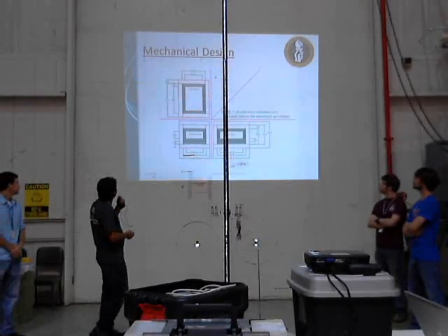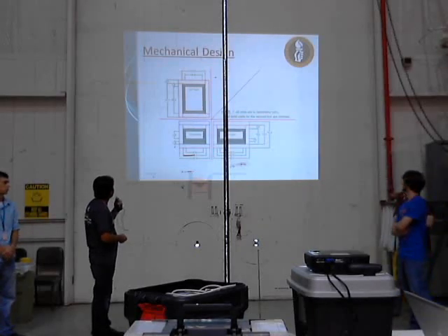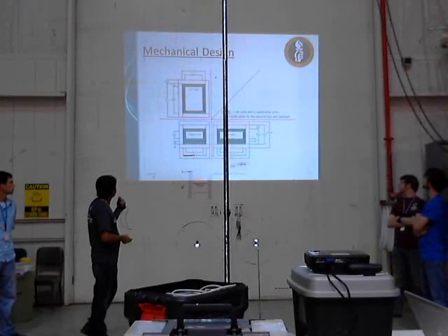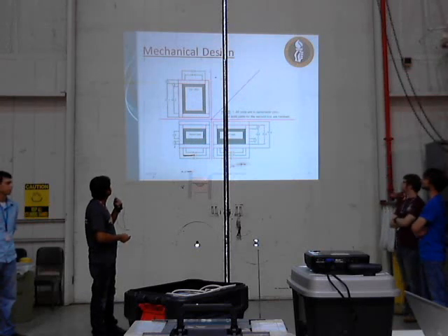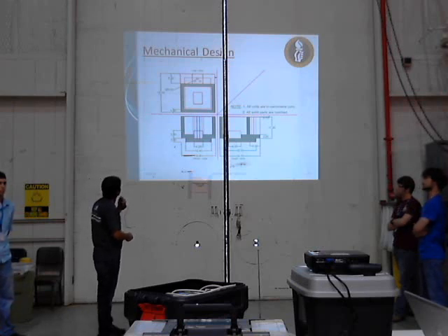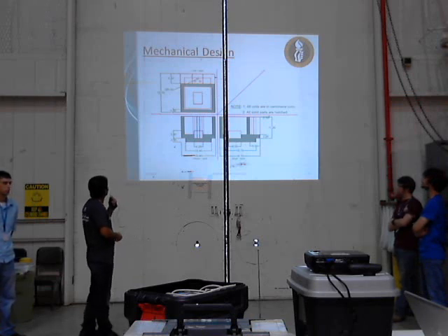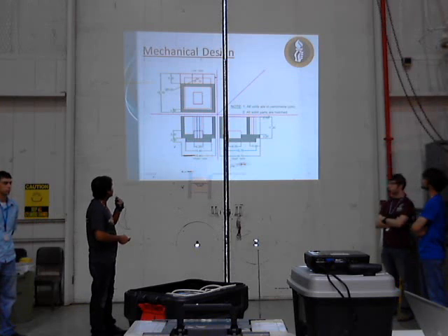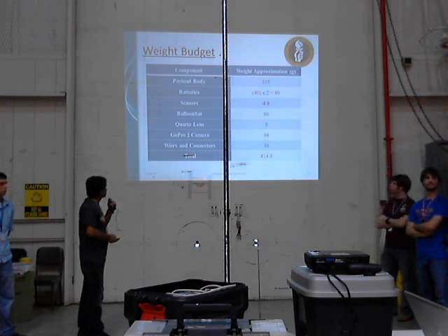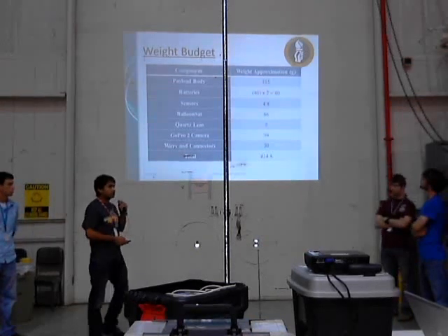We have one outer box of 2 centimeters of styrofoam, and the inner one is 1.5 centimeters, and the dimensions will be 16.4 by 9.7 by 14.4 centimeters. There will be one extra layer of styrofoam protruding out of the outer box where the camera will be placed in between, and it has a height of 9.2 centimeters. Based on all the materials we used, the total weight came out to be 414.8 grams, which is well within the weight limit of license constraints.